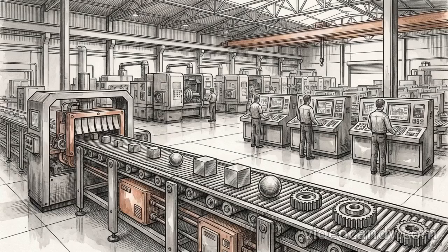Now that the system is stable, you can consult your manufacturer's documentation to optimize your V per hertz curves and sleep modes for long-term energy savings. Systematic isolation takes the guesswork out of troubleshooting. It shifts daily operations from reacting to sudden maintenance headaches to maintaining a predictable, efficient process.